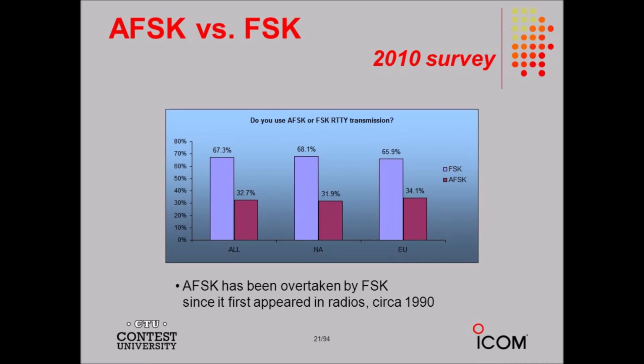The balanced modulator produces a double sideband suppressed carrier, DSBSC signal, often called simply double sideband. One of the sidebands can be suppressed in a subsequent circuit by a bandpass filter to obtain an SSB signal.